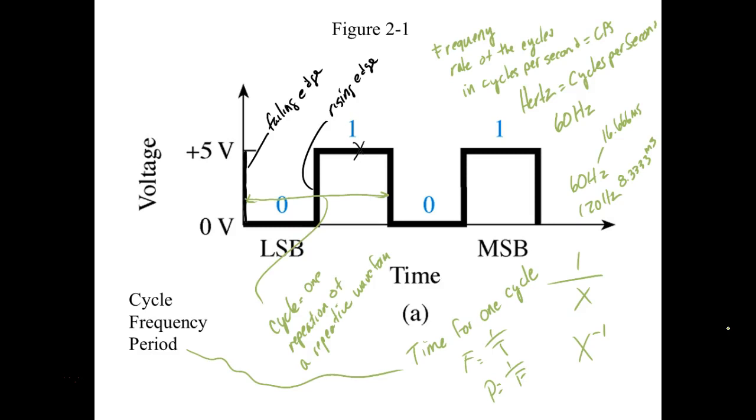So that's 100 microseconds, and we had what, 4 of them? I think we had 6. So it'd be 600 microseconds. If I wanted to know the frequency, then I would just hit the reciprocal key on my calculator, and that would give me the frequency. We should be close to 1,700 hertz.